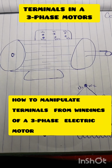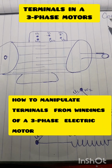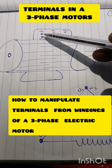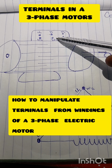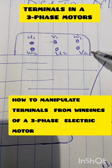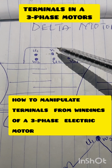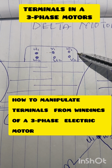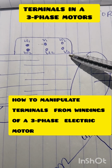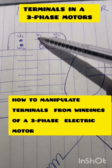Now, just like I explained to us that a three-phase motor has six terminals. Those six terminals are these: 1, 2, 3, 4, 5, 6. And these terminals are usually labeled U1, V1, W1, W2, U2, and V2. How do we arrive at these six terminals?